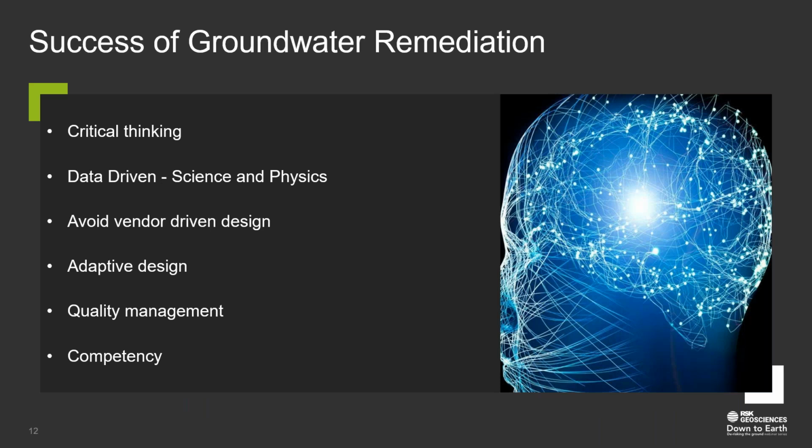And then, if possible, avoid vendor-driven design. The solution should be tailored to site-specific conditions rather than product availability. So it would be better to assess the whole spectrum of remediation options available rather than limiting to a vendor's capability. And then the adaptive designs, very important, to keep the project flexible, allowing adjustment as new information emerges.